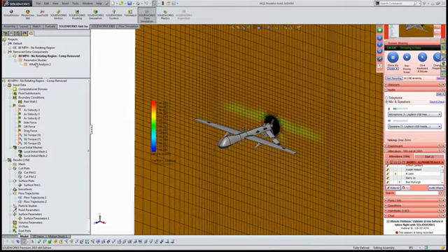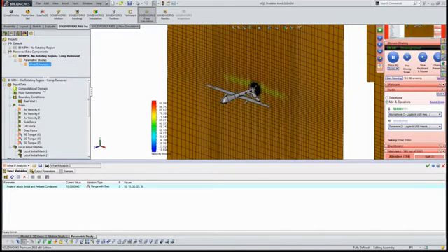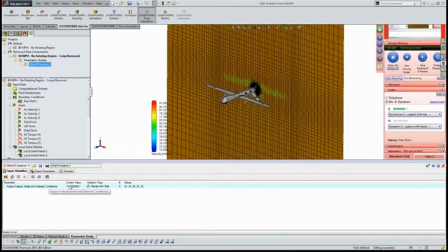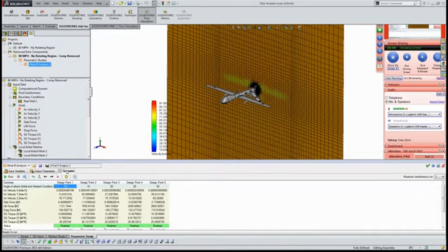Now what I did do in this case is I ran a what-if study. And just so you understand, your what-if study doesn't just have to have one parameter. In the first one, the parameter was the length of the wing. And in this one, I'm changing the angle of attack from 10 to 30 degrees. You could include both of them at once, and you could have multiple input parameters. It's just going to create a design of experiment and run all of those different design points for you. So, depending on the complexity, this could be something that you maybe would run over the weekend, or, like I said, I live in Southern California, so maybe do it over lunch and go surfing or whatever it is you like to do, because your boss is going to come in there and see that your computer's running, so you're going to be in fine shape.